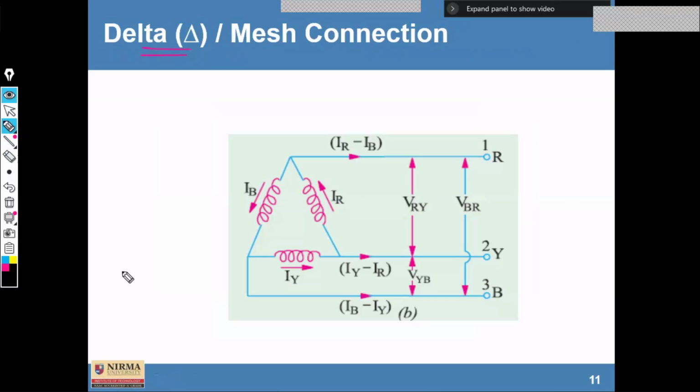When there is a balanced system, normally these kinds of connections are required. Why are delta and star connections required? Because ultimately it reduces the number of wires used for transmitting the same amount of power. Here, instead of 6 wires, we can use 3 or 4. Clear? So this is a benefit of transmitting the power without any complex circuitry.